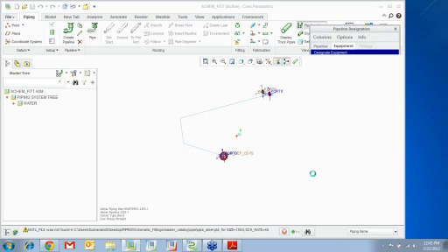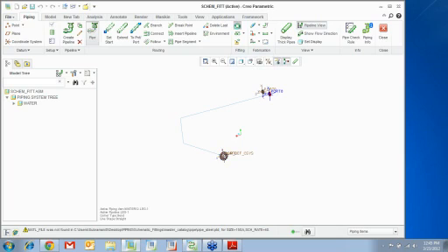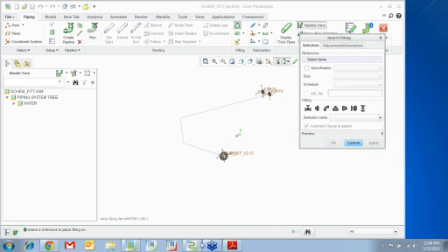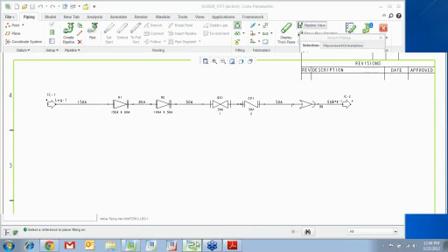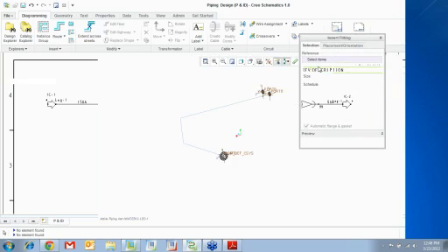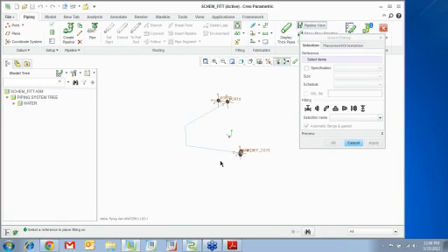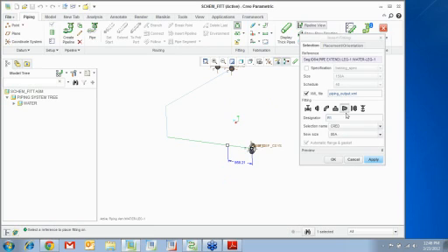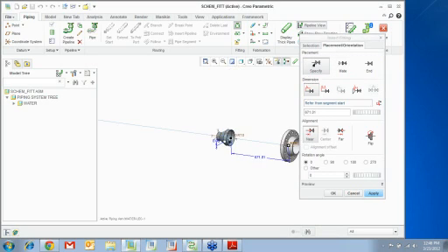So now I'm going to insert a fitting. So let's see the order of the fittings also in here: reducer, gate valve, check valve. Okay. So note that I'm not picking anything from here. All I do is click. It defaults to the reducer and it picks the right size for me. See that? When I go to placement, you can move it around.